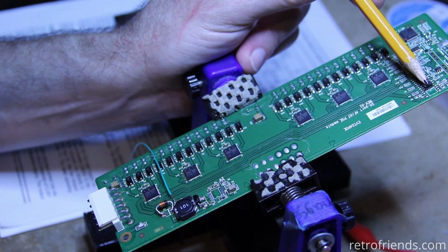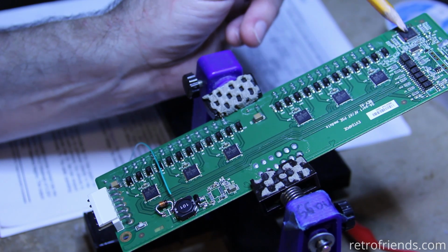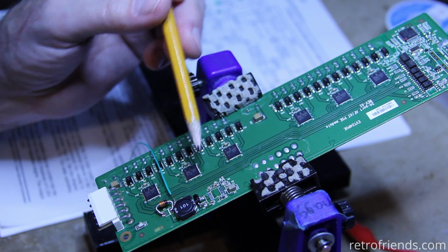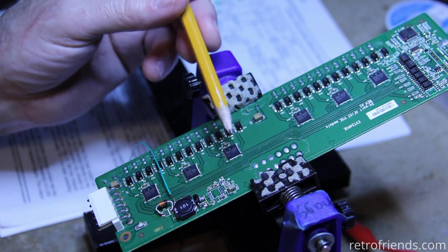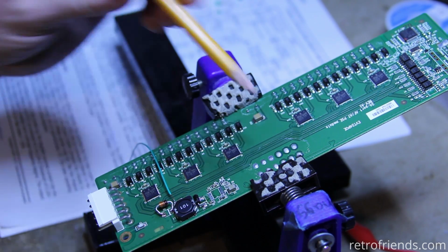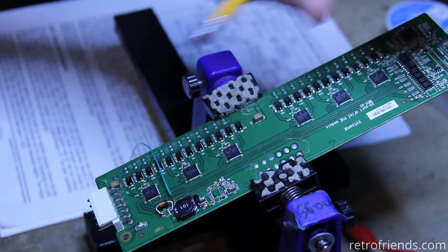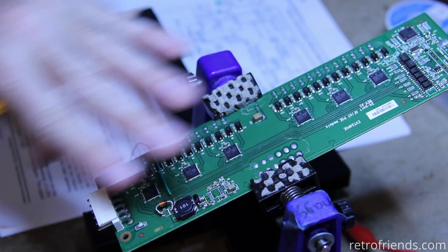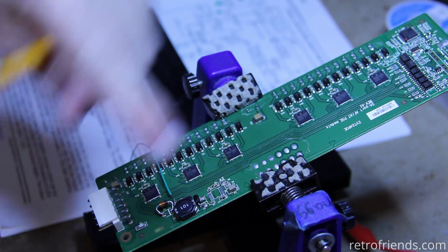The 5 volts powers these optocouplers and probably this chip here, which I don't even know what it is, and these controller chips. So they just get power through a via. There's a via right next to the power pin, and it just goes into the board. So that tells me that there's a 5 volt plane on this board, an easy way to distribute 5 volts, because basically you need it from one end of the board to the other.